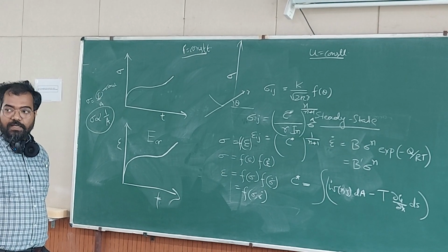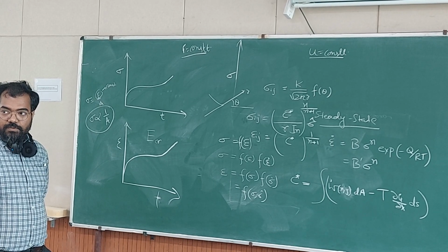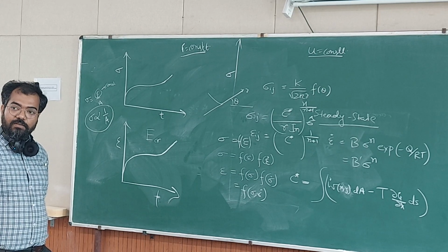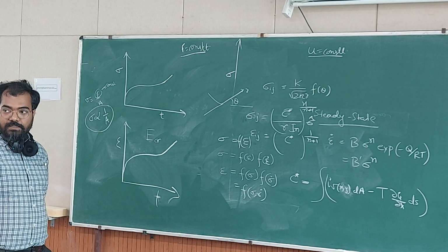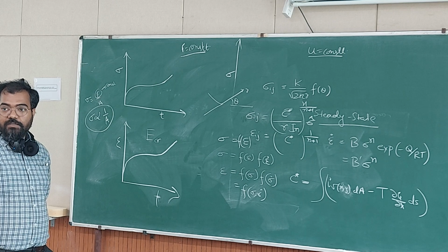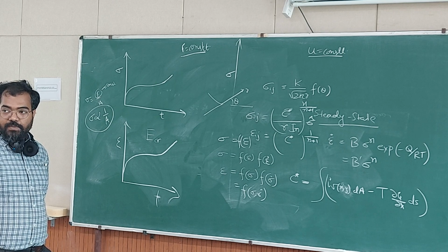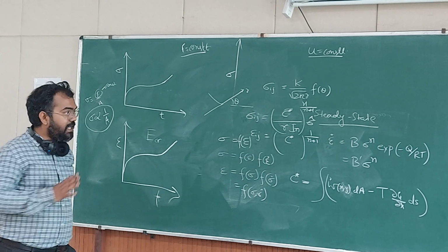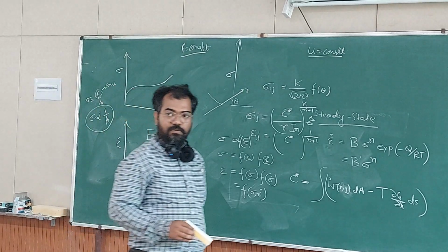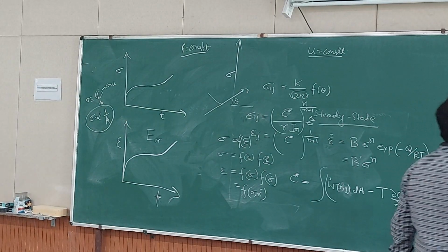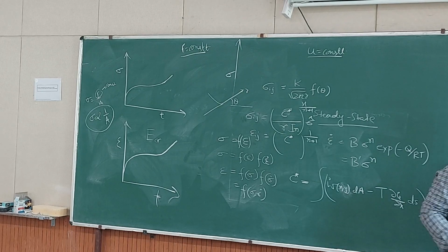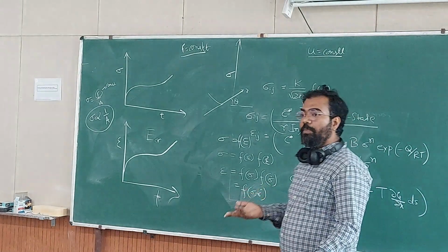What is C star defining? So if J can define that this much energy is required for a unit crack growth, then it is defining the energy requirement, so energy release rate. But what is C star defining? J is the energy release rate, right? And what will happen if you apply J in time dependent deformation? What will happen? What wrong will I do? It will not be path independent, fine.